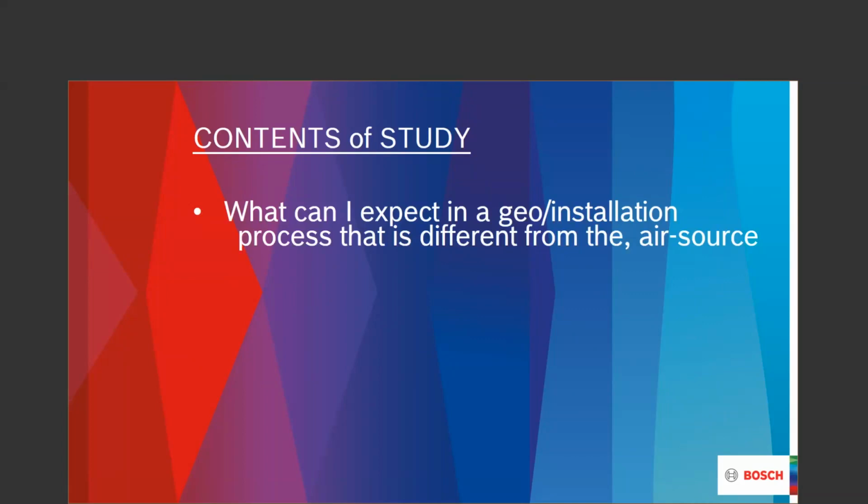It may be an upflow. It may be a vertical situation, but the return, which would be on the bottom of an air handler, is now going to be on the left-hand side or the right-hand side. So the physical cabinetry spacing that we're going to need, whether this system is in the attic or in a closet or in a basement of some type, it has to be thought about. So I can expect some differential of a location in a structure type scenario.